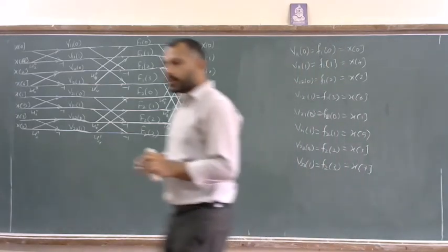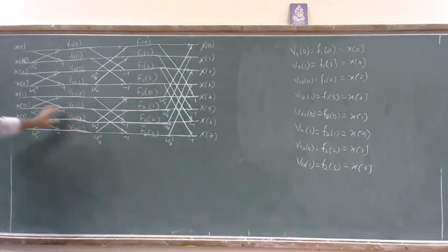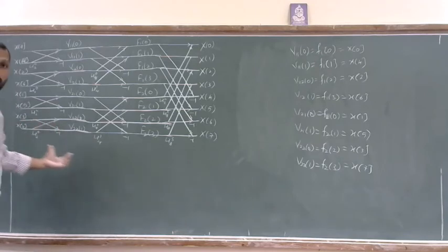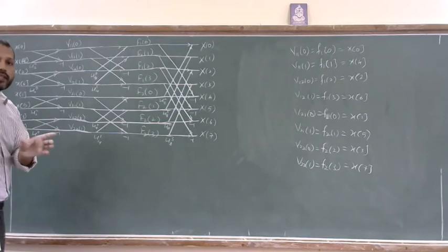The concept is very simple. From the given n-point discrete time sequence, that sequence will be successively decomposed to the smallest size for which we can calculate the DFT, which here is the 2-point DFT. To calculate the 2-point DFT, the n-point sequence will be divided into 2-point sequences.